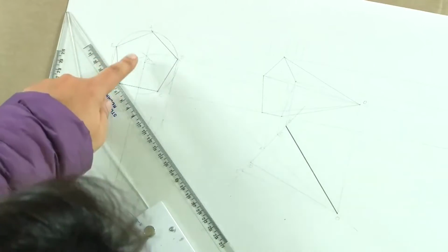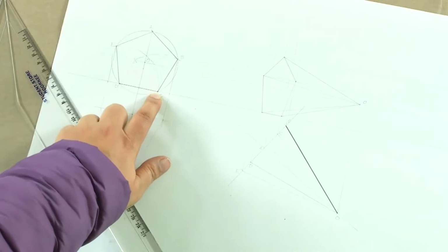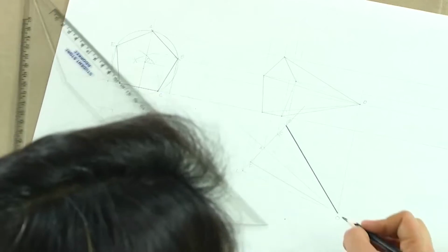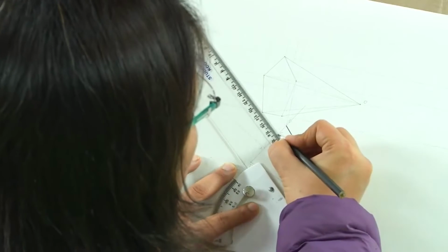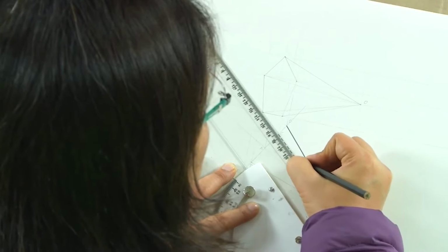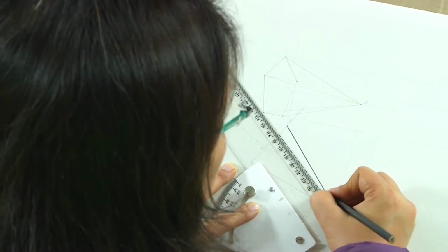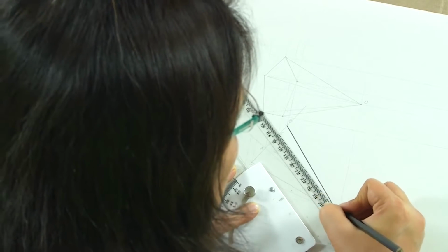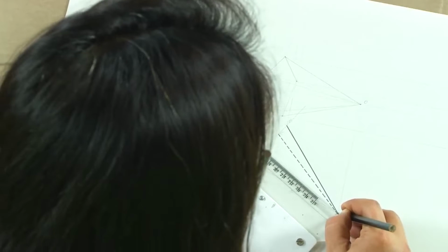OB. Now, if you see this from the top, we will not be seeing the OC and OD. This is a hidden line. So, how do we draw the hidden line? If you remember, we draw hidden lines by equal sized dashes. So, it is a dashed line which is used to represent a hidden line, which is what we are drawing here. OA is visible.